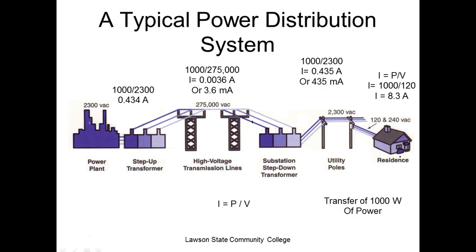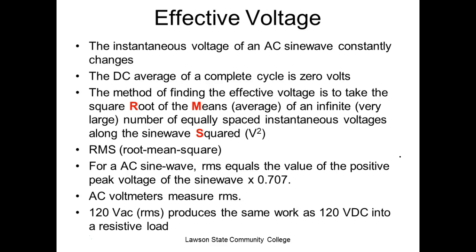So you get some of these big companies running big high horsepower motors. They're going to run them on high voltage, and the motors are designed around a high voltage, because now they can run smaller conductors out there. So we have 208 and we have 120. We're going to use 120 for our control voltage and 208 for our power voltage. That motor right there is a dual voltage motor, and we'll talk about it later on.